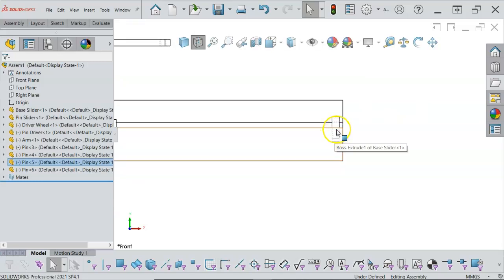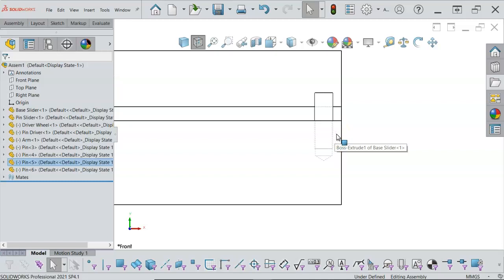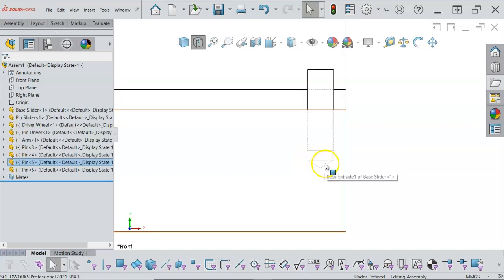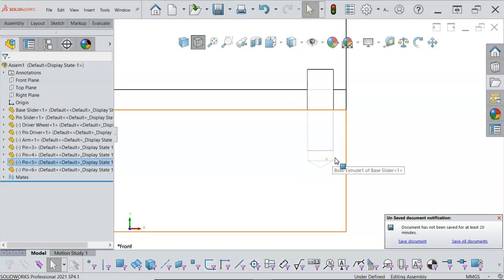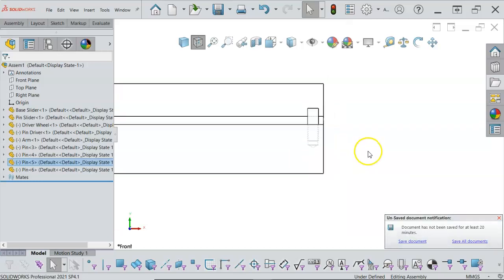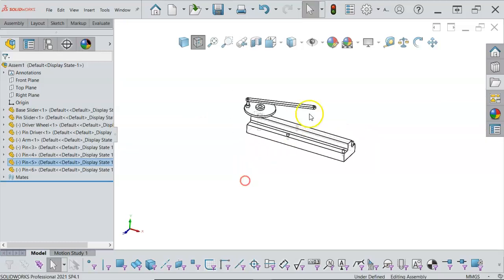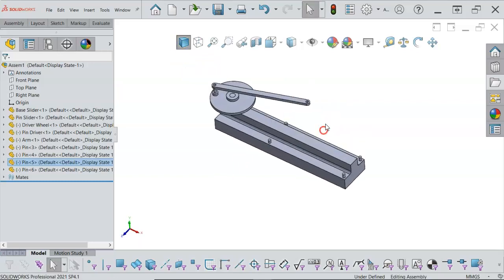But really in our process, if this is going to be a press, and whatever tolerances we put into the drawing, the drill has the drill point, a little bit of a lead. The reamer probably has 1.5 millimeters or 60 thousandths of lead on it that helps the tool start and align to the hole. So we're not really going to get all the way to the bottom. So as long as we have the clearances from the top and the bottom of the hole, pins can be pressed in until they seat, and it will work just fine.